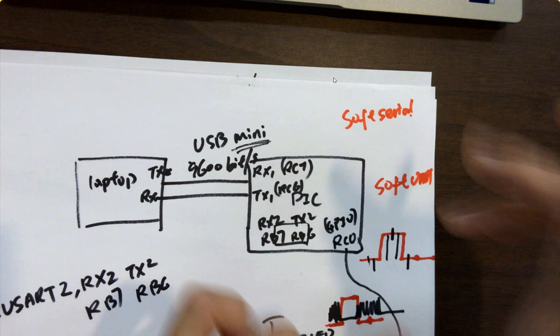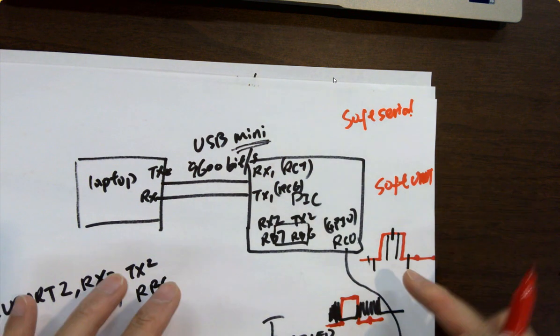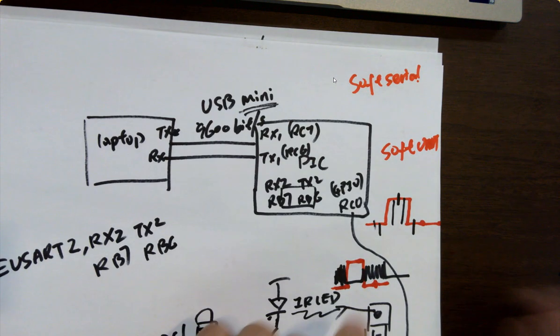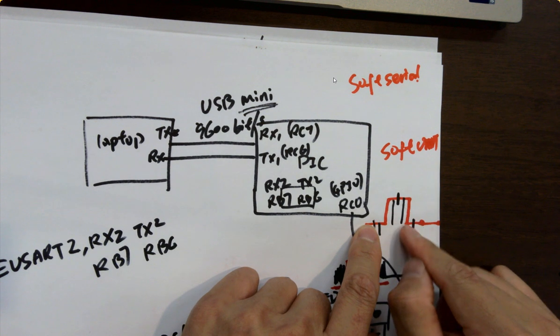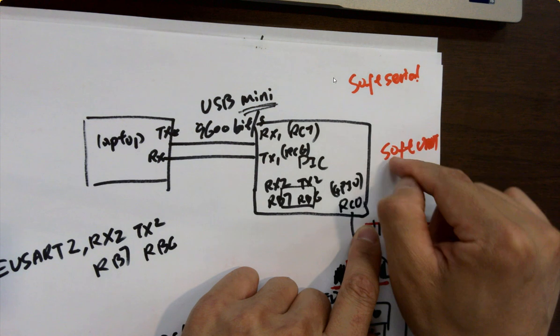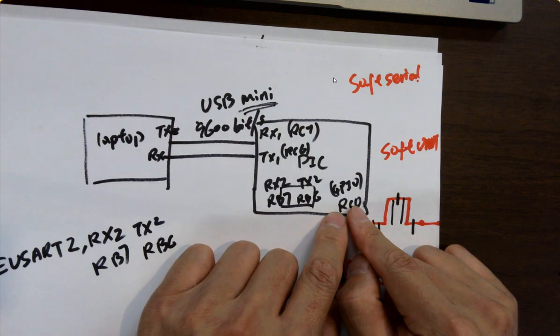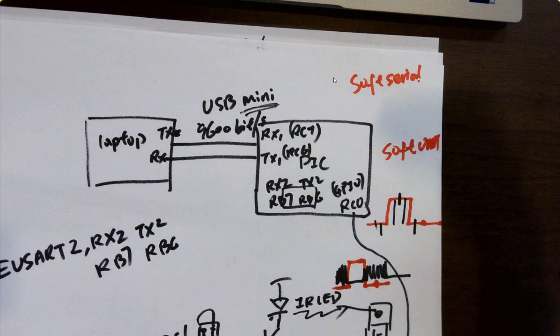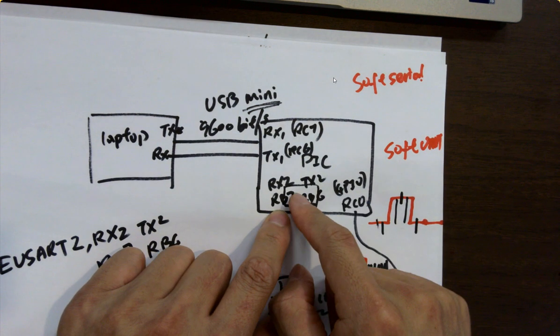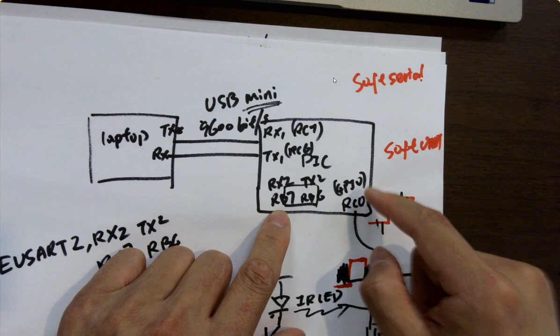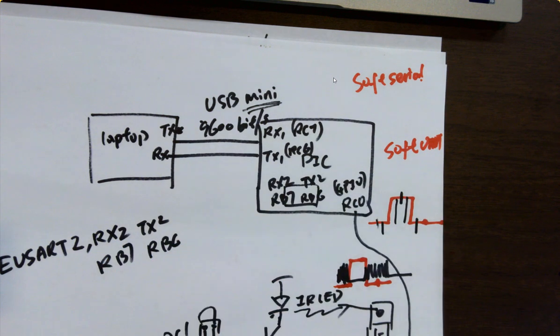Yeah, you can write code to deal with the timing. It's something like you read it, you delay it, and then you read it again. So you can code it into your software to make this a UART. You can do UART with Verilog, synthesize and fabricate it in the chip as a digital block. If you don't have that, with GPIOs you can also write RX and TX, since you know the timing. Simple, right?